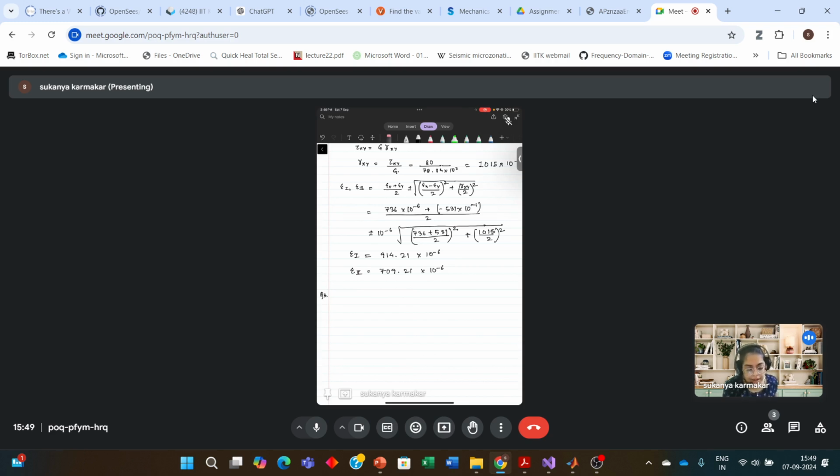How much change in length would occur if the material yielded? The material yields at 250 MPa, and we have to use the maximum shear stress criteria, that is the Tresca criteria, and the relationships for the thin wall pressure vessel. We'll have to use them.